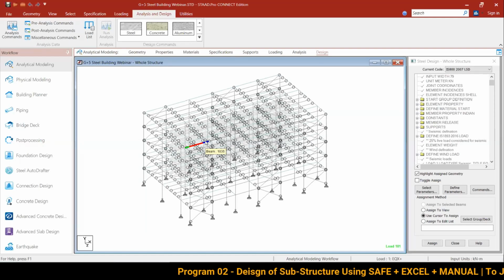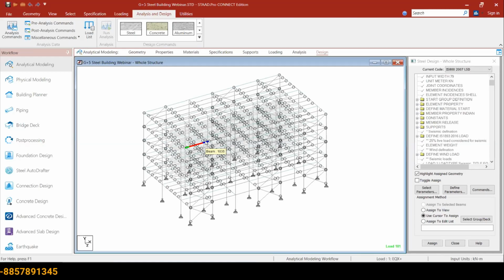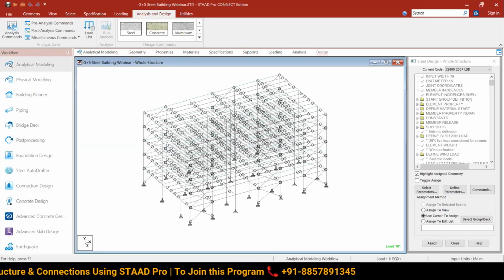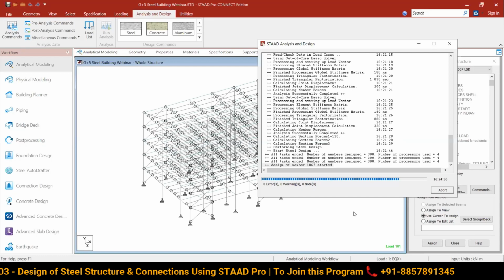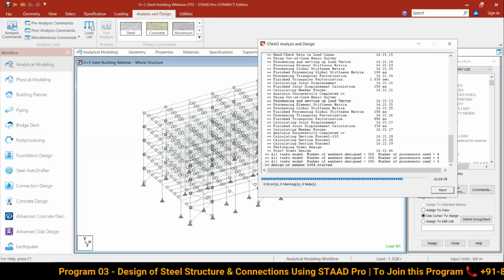So depending on the height of my wall, the length of my member will change. But in the other direction, Lz, where I do not have any wall, I will have the complete height of my column. For example, it could be 5 meters or 4.5 meters. So this depends on the structure. For example, if we take this main beam,